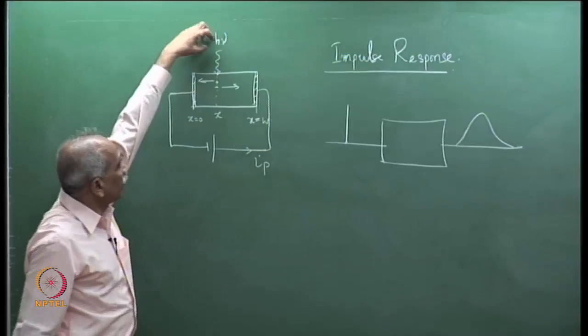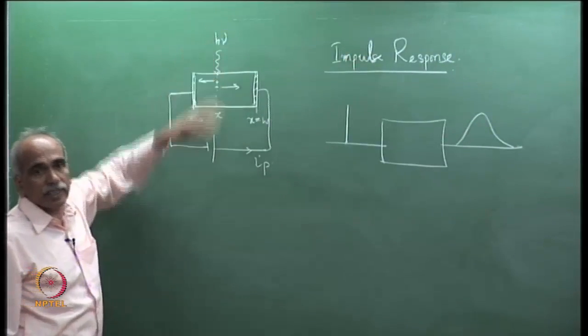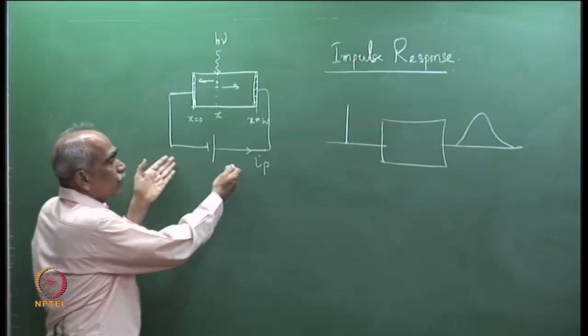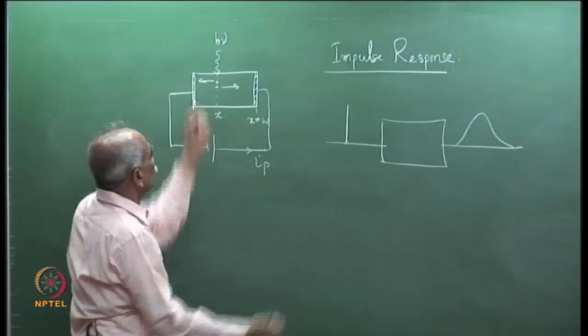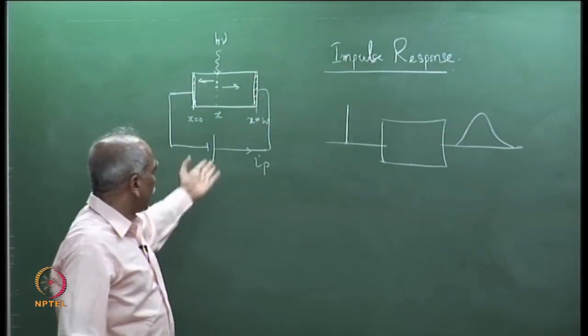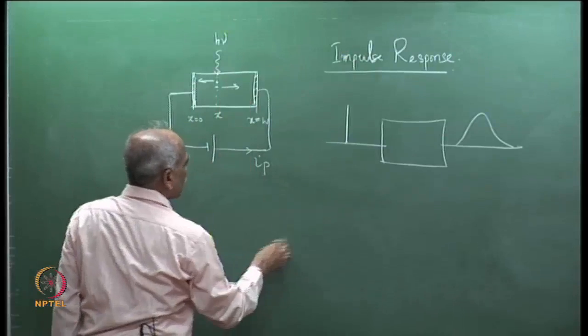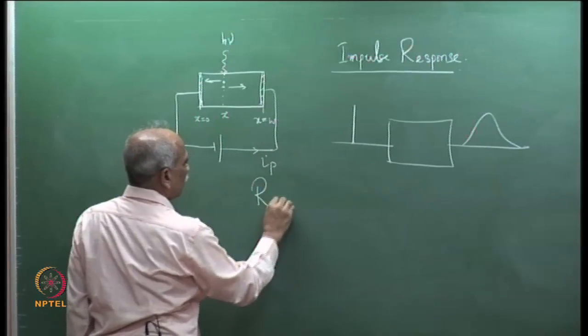So, at an instant t, instantaneously one photon is incident. We want to see how the current would look like. So, the photon is incident at one instant, how would the current in the external circuit look like? The current in the external circuit is given by Ramo's theorem.